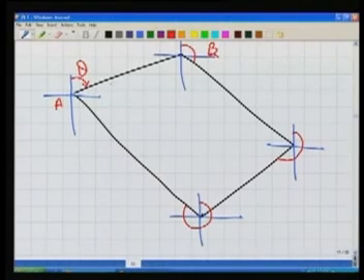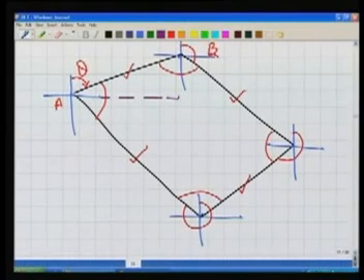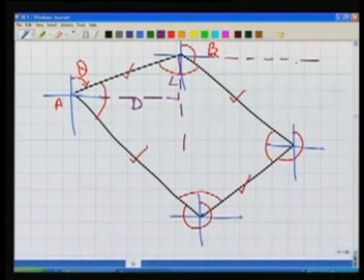Then we had measured the internal angles, this angle, this angle, this angle, and this angle, using the theodolite or total station. As well, we know these lengths, using the EDMI or the chain. Having known these things, we can very easily compute for each and every line the corresponding latitude and departure. So this will be the value of latitude and this will be the value of departure. Similarly here, just take care the sign will change.